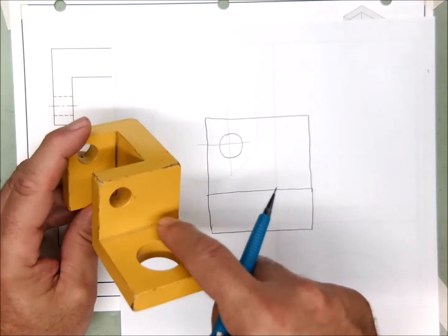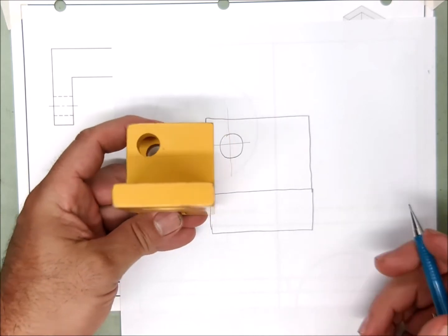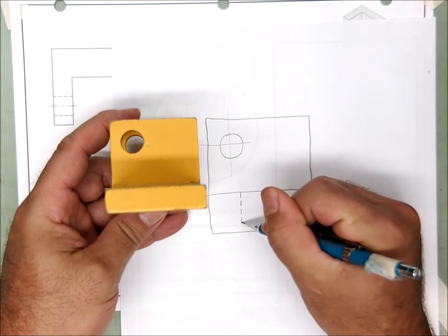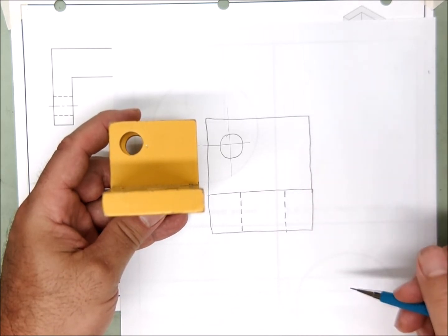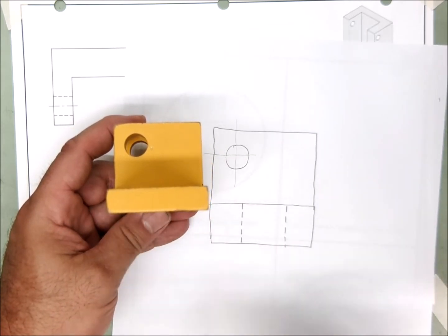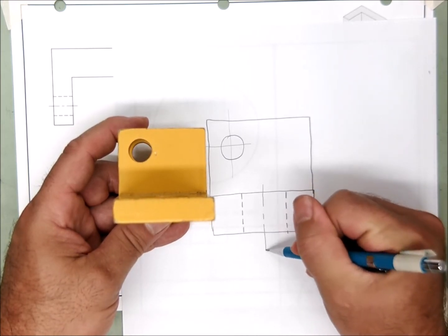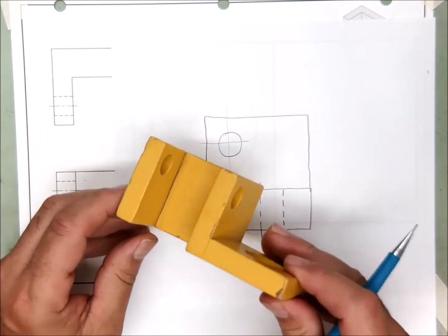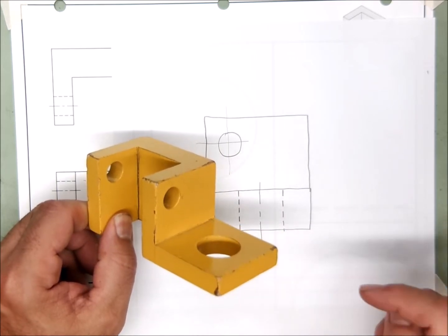Well, we don't see the big hole over here, do we? We don't. And what we probably remember is the edges of the hole will create a tunnel in the views where you want to show the hole, but it's not circular. So there's a tunnel going through here that we can't see, right? And then of course this is a cylinder, so it should get a center line. Is there anything else we wouldn't see if we were standing here looking in this direction at that right side?